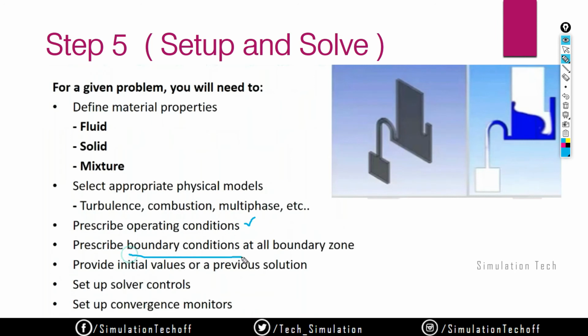You also need to define the boundary conditions. We will explain these things when we enter the CFD environment, the GUI, so I will explain in that condition. Then the initial values and previous solution, set up the solver controls, and you look at the convergence monitor. So those are the steps involved in setup and solve.